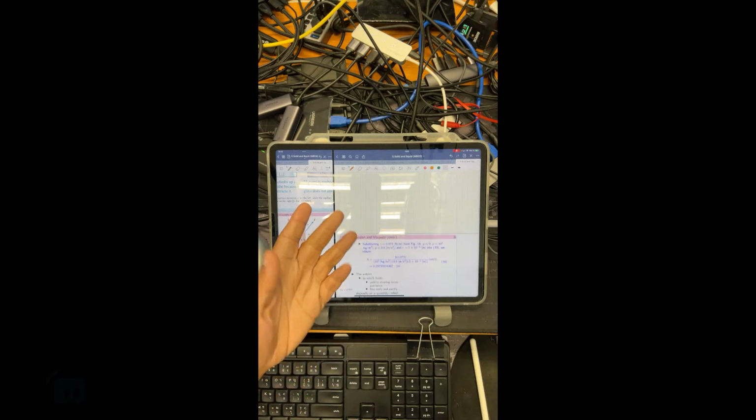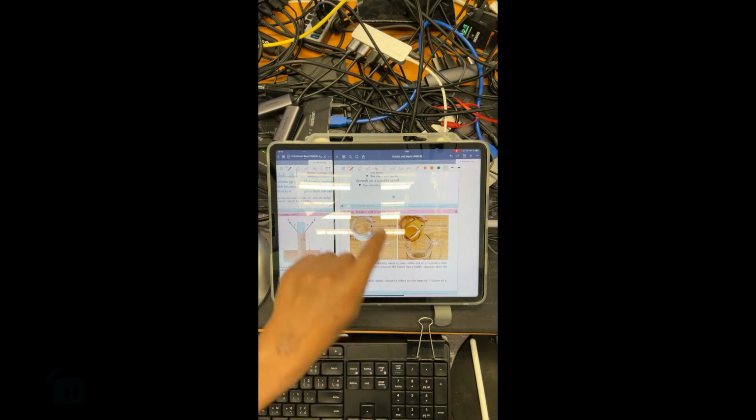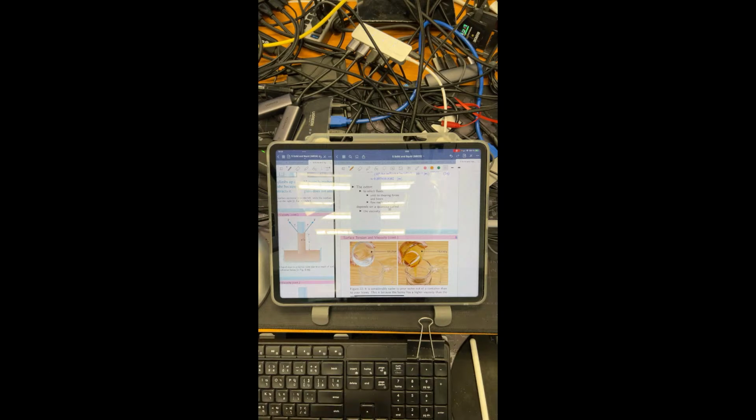Surface tension has been considered before, right? And now we arrive at the second term, which is viscosity. Viscosity is the following. Let's get into the meaning of viscosity. The extent, the amount or the quantity to which fluids yield to shearing forces and hence flow easily and quickly depends on a quantity called the viscosity. Viscosity is like the friction at different layers of fluid. Even if you see a single piece of fluid, there are different layers of fluid, and among different layers of liquid there are friction forces, or shearing forces, and those shearing forces will cause the viscosity.